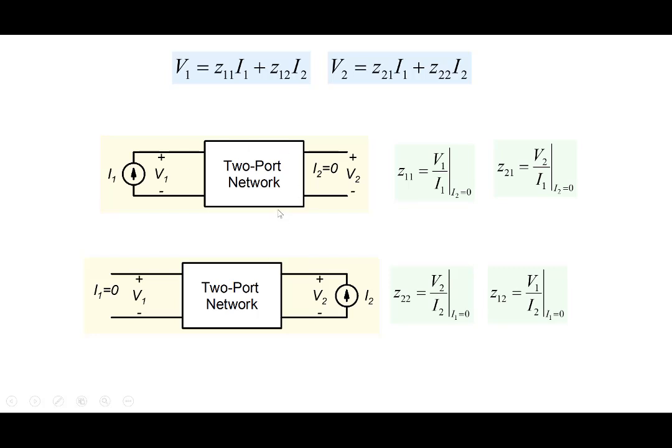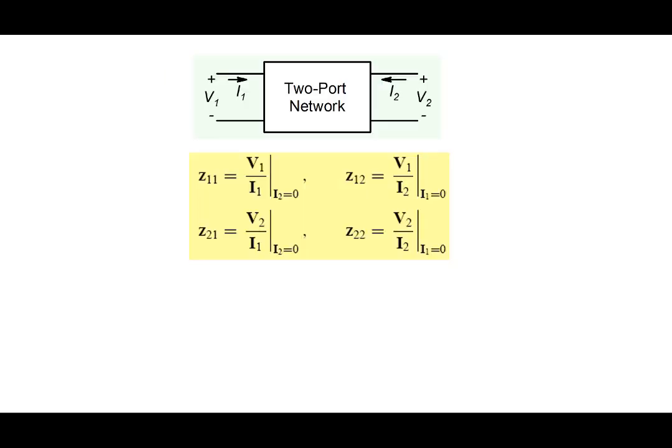So with any unknown device, a transistor or something else, suppose somebody has invented a new transistor and a model for it has not been built yet, you could take that transistor and experimentally measure Z11, Z21, Z22, Z12, and thereby you have a representation of the transistor. That representation you could deploy anywhere in your circuit and determine what the circuit performance is going to be.